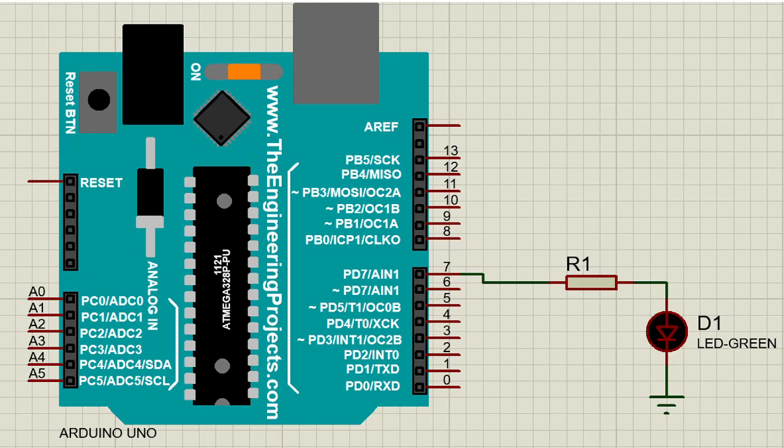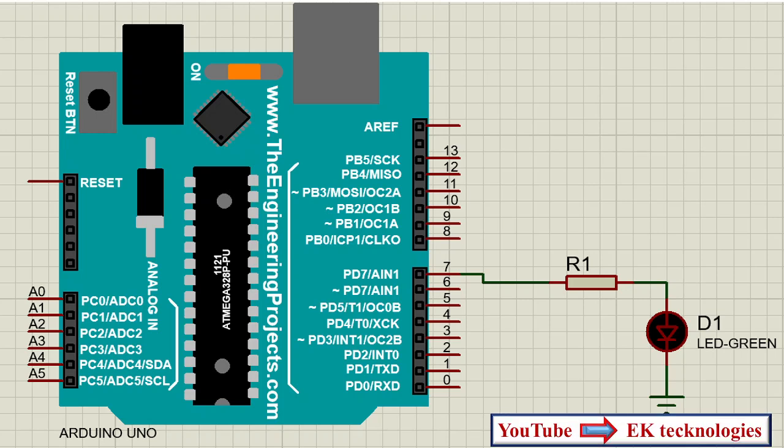It is essential to note that an LED is driven by current. So the LED has a capability of drawing the current which the source produces, even much more than what it requires to turn on, and so the LED can be destroyed. So a limiting resistor is very, very much essential to limit the amount of current flowing to the LED.